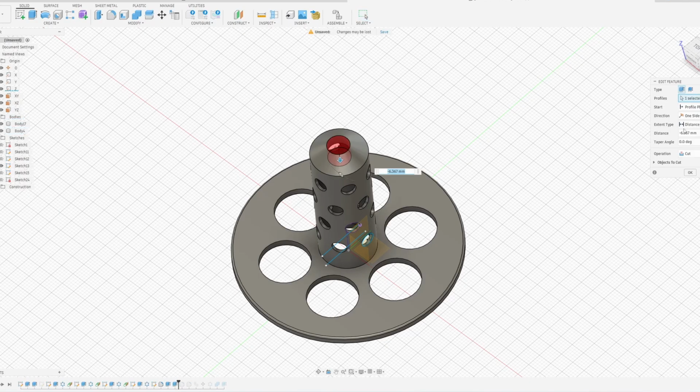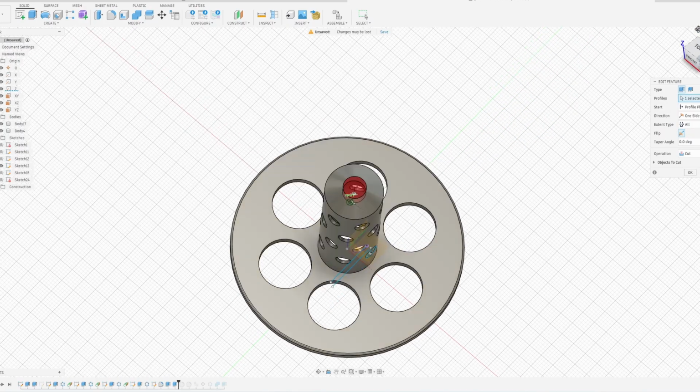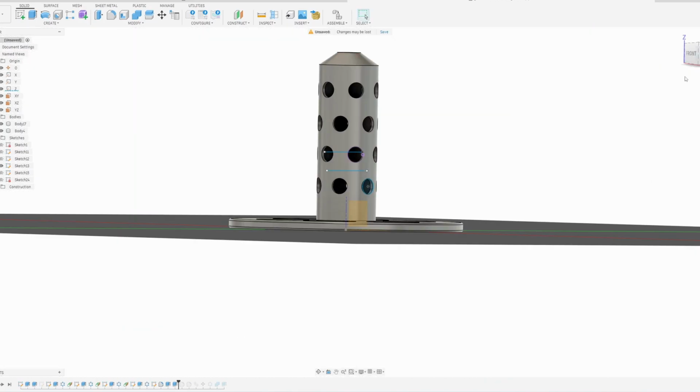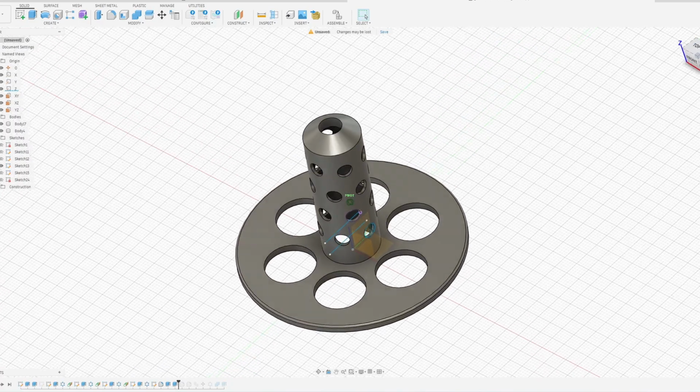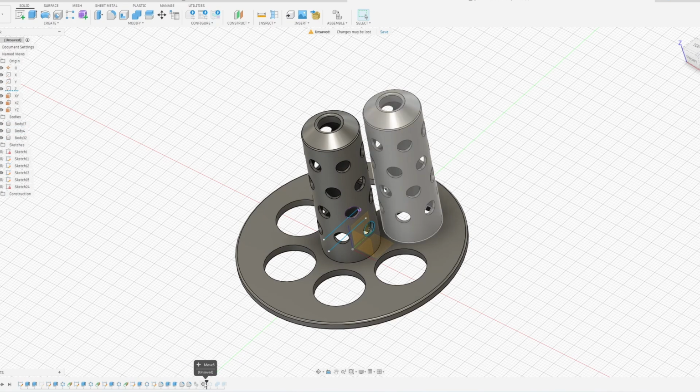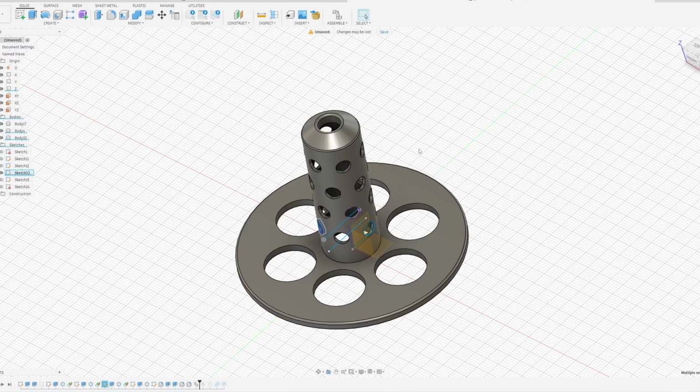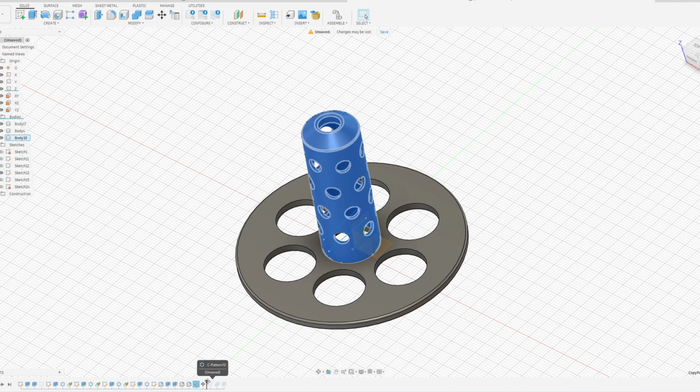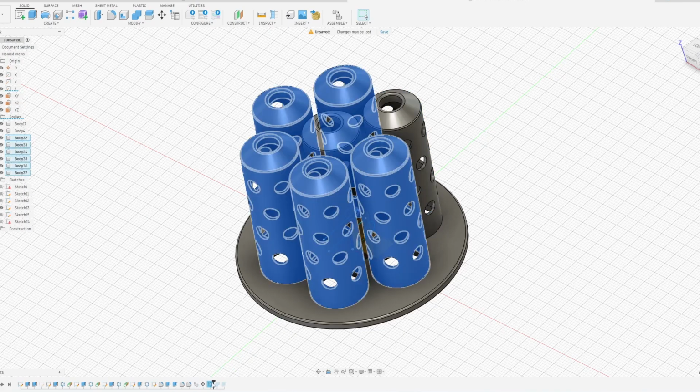For this one, you can also put all, and it's going to cut through until the last little piece that it encounters in there. Then we're going to smooth the edges from the top and this edge around here, and then we're going to move. So we're going to grab this feature right here, and we're going to, oops, not yet.